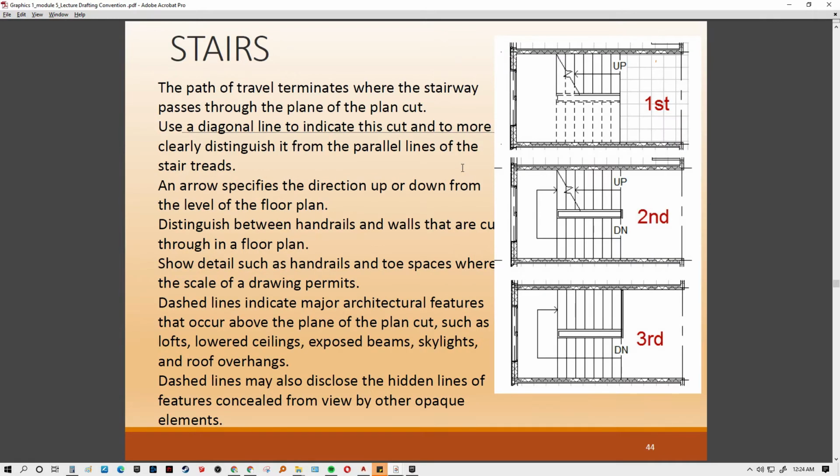In breaking the staircase, usually it is 10 steps. This is because each step must be at 0.18 meter of height. So 10 times 0.18 is 1.8.